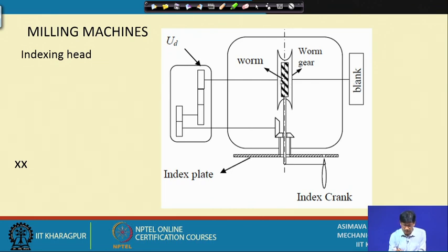Now, what we do is, we extend this shaft connecting the worm gear with the blank backwards and take a feedback. We pass it through a gearbox. Okay. Remember gearboxes? So, gearboxes will be giving simply a changed rotations per minute at the output in relation with the input. I get a changed value here, and with the help of two bevel gears, I rotate the index plate.